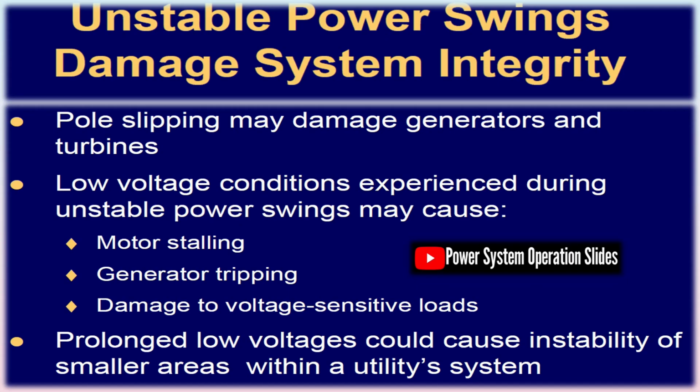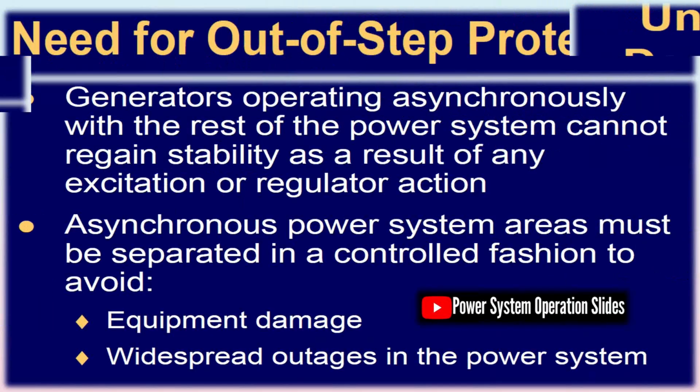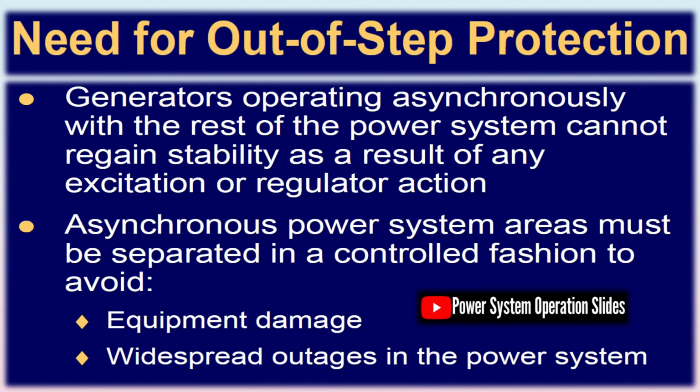Following a transient fault, the system is typically returned to service after a controlled trip and reclosure, with the power angle curve shifting to reflect the pre-fault, fault, and post-fault operating states. This detailed understanding of power system behavior under various disturbances underscores the importance of using precision protection schemes like OST and OSB to maintain stability and reliability in modern electric grids.